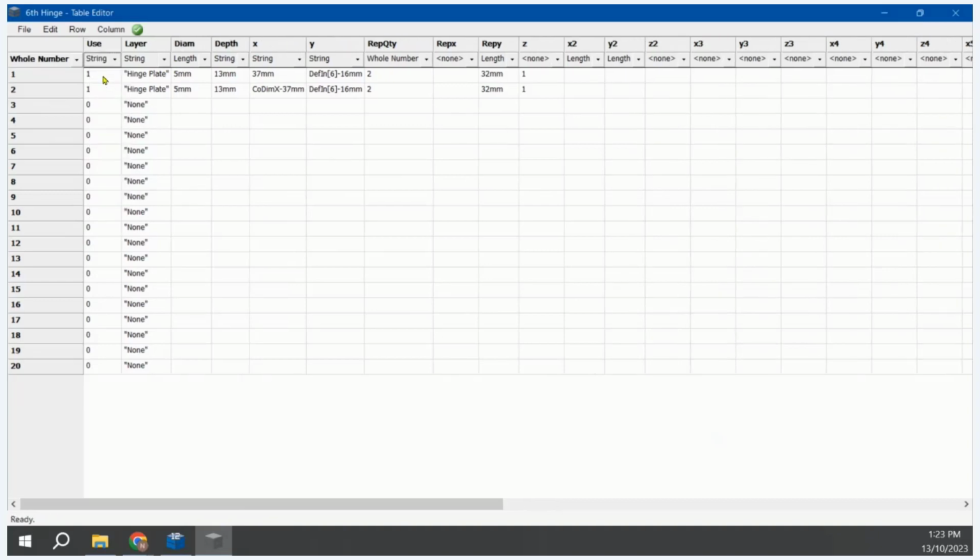So in line 1, we're going to put if open bracket, sec part name equals apostrophe ENL apostrophe close bracket, then 1 else 0. Now this needs to be absolutely spot on. If it's not correct, it won't work. We'll click tab and we'll just move that across.